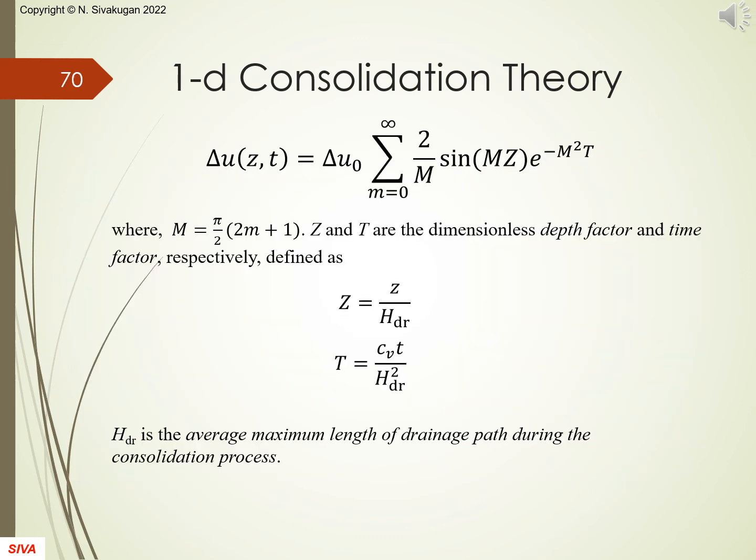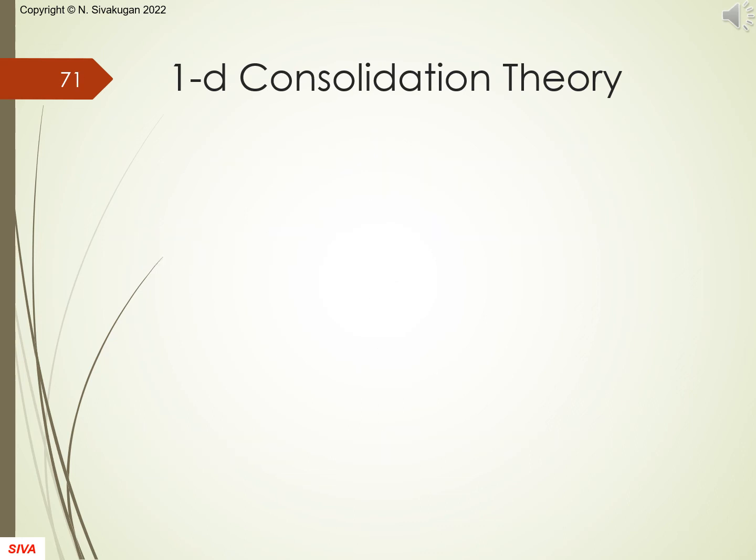Here, we have the final solution for Δu over Δu0 as a function of depth factor, big Z, and time factor, big T. These two factors are dimensionless.